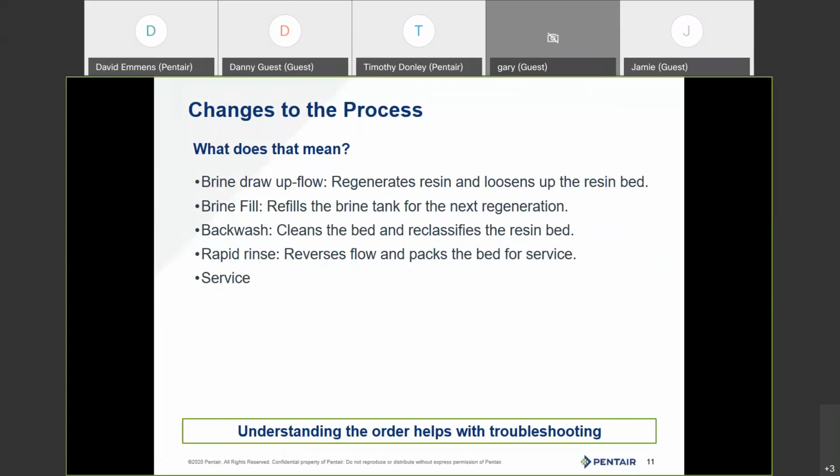The same sort of elution studies apply to upflow brining as downflow, but it's critical to understand with upflow that you need soft water regen or separate source regeneration to extract the efficiencies out of it, but it does work. So it's just a different tool, a different way to exploit resin technologies. It's a different way to squeeze some more efficiency out of the same equipment.